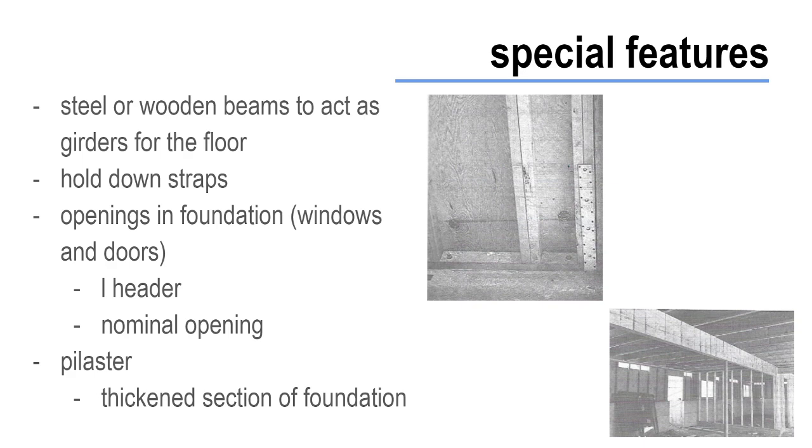But anyhow, now if windows are included in the foundation or any openings, then the form carpenter or the mason has to provide those openings to the proper size. So the locations of those windows are dimensioned on the foundation plan, and the size of the windows may be given in a note or in a window schedule.